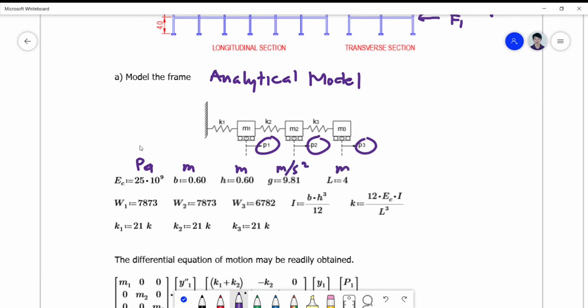Okay, so our unit is actually consistent in Newton, meter, and second square format, such that you don't need to worry about conversion later, so you must be able to use a consistent unit. That's why in software we are to set the units first prior to modeling.